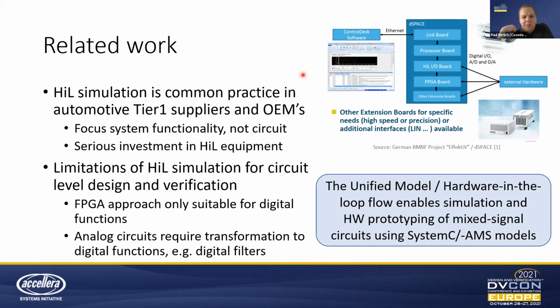As Morten said, hardware in the loop was heavily used in the automotive industry, Tier 1 and OEM. The typical HIL systems there are dSPACE systems working together with MATLAB. They put whole ECUs with firmware in the loop, and then they simulate the environment around this hardware piece.